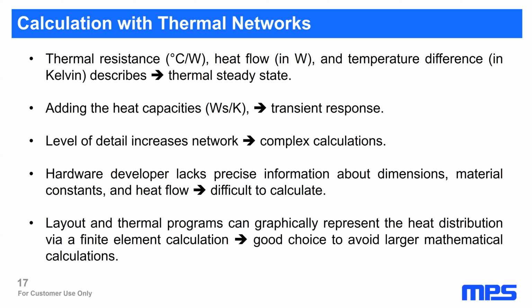As the level of detail increases, the network becomes a complex calculation. Remember the circuit, it's very hard. You don't know the variables exactly. The hardware developer lacks precise information about dimensions, material constants, and heat flow. Difficult to calculate. The best way: layout and thermal programs can graphically represent the heat distribution via finite element calculation, a good choice to avoid larger mathematical calculations.